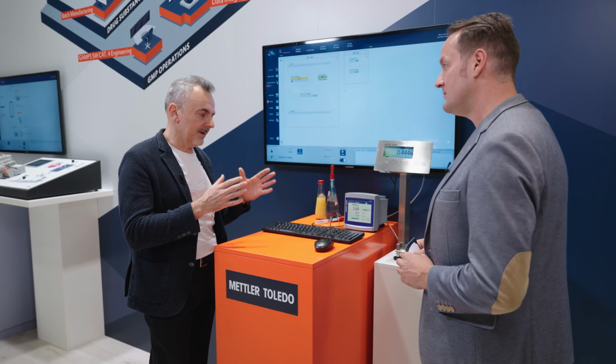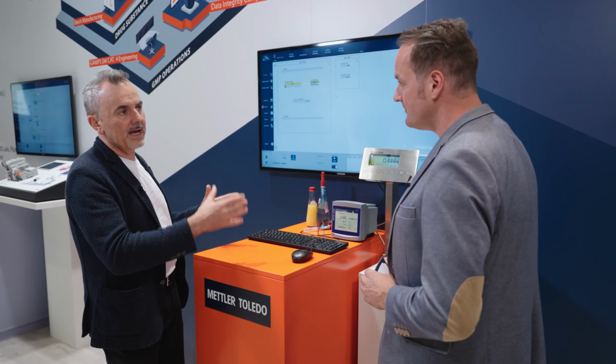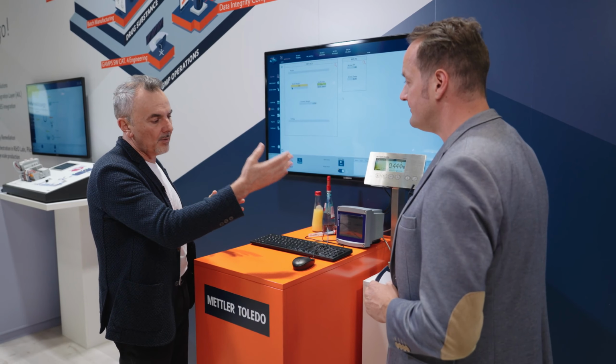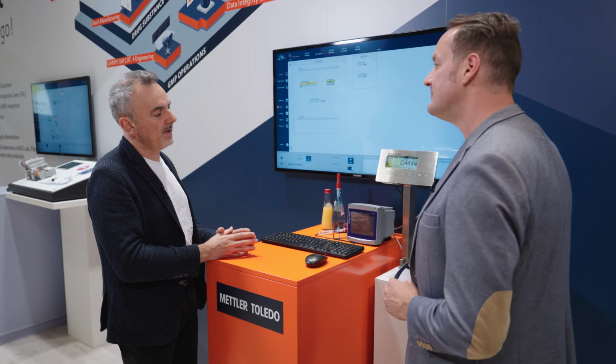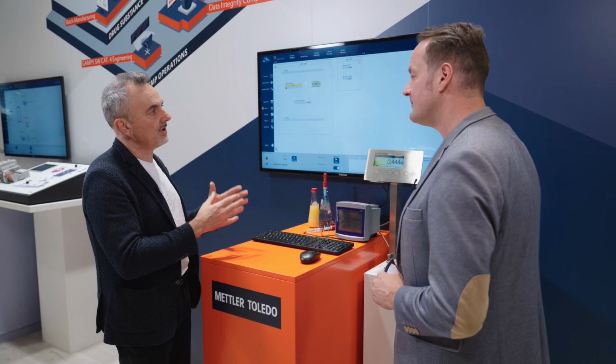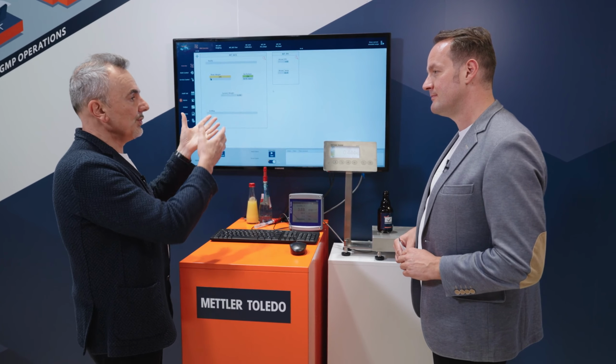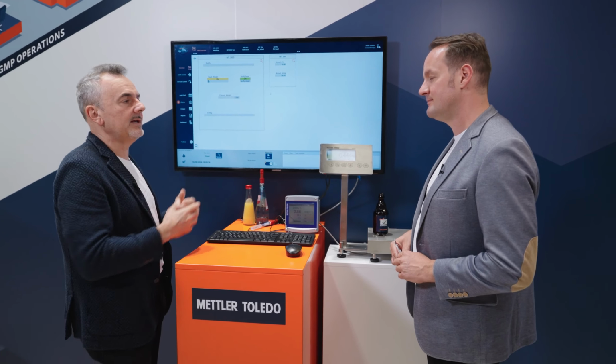So what detailed use case are you showing here with this device? We are showing an example of in-process control. This is a typical activity you have to do during production. During production, you have to take some samples and measure their characteristics. It can be a weight, a pH, or other information. So we leverage the MTP integration exactly for creating a recipe in process control. In this recipe, we combine communication with the devices on one side, communication with the operator on the other side, and finally phases for storing values in our audit trail or maybe in an MES.